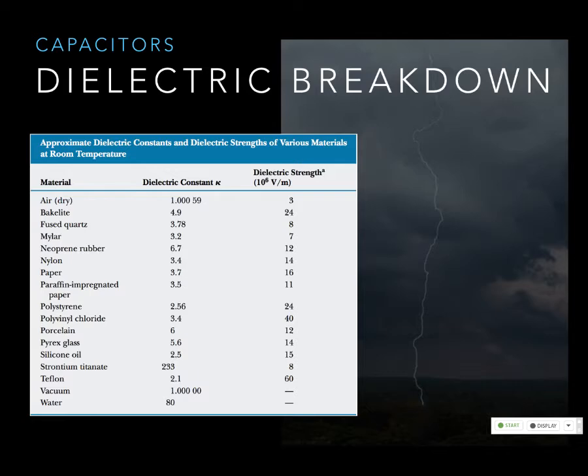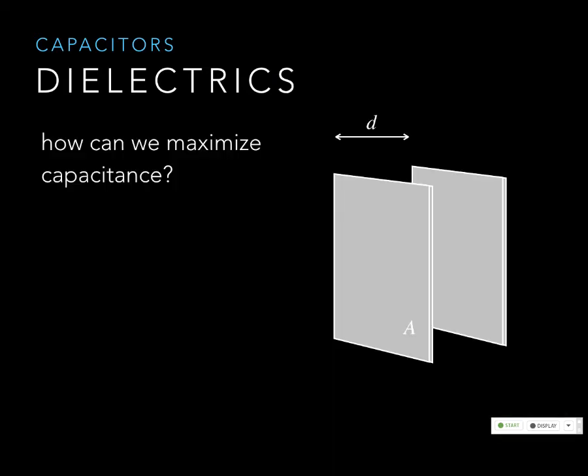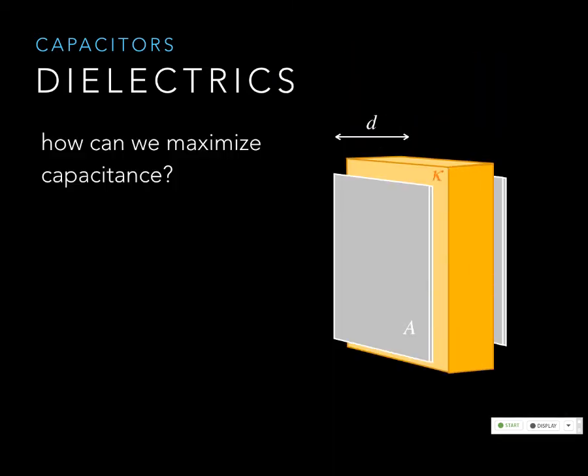And so this affects all of the things we did that involve epsilon naught, but primarily capacitors, okay? So that's just what I want you to think of. Because otherwise, it gets really confusing where you put kappa. The place you put kappa is always next to epsilon naught, okay? So this makes capacitance bigger, right? The bigger the kappa, the bigger the capacitance without changing anything else, all right?